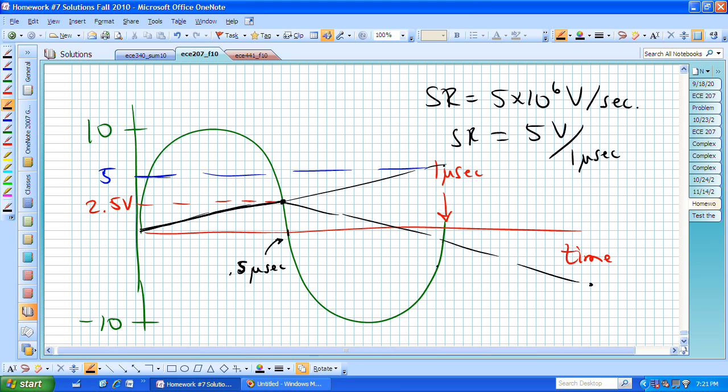This is not going to be very accurately drawn, but that's where we would get to. And I hope you can see that this is going to be a triangular waveform that's varying between a maximum amplitude of, or its output waveform really is limited to 2.5 volts.